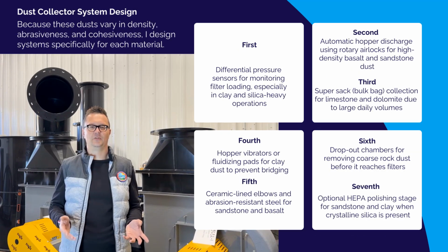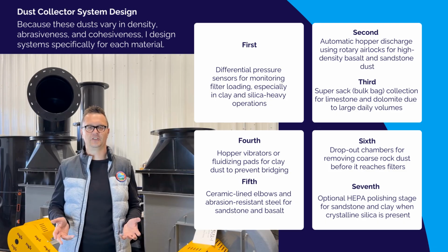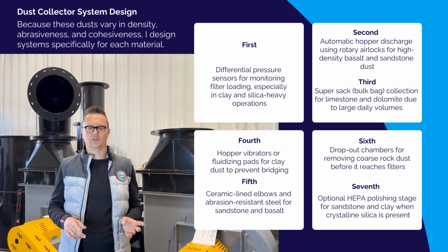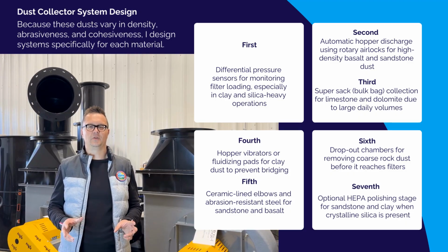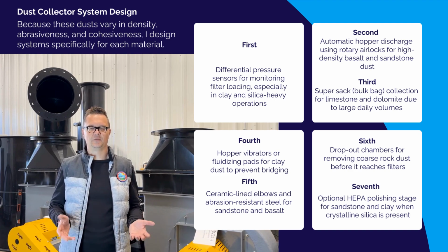Dust collector system design. Because these dusts vary in density, abrasiveness, and cohesiveness, I designed systems specifically for each material. First, differential pressure sensors for monitoring filter loading, especially in clay and silica-heavy operations. Second, automatic hopper discharge using rotary airlocks for high-density basalt and sandstone dust. Third, super sack bulk bag collection for limestone and dolomite due to large daily volumes.